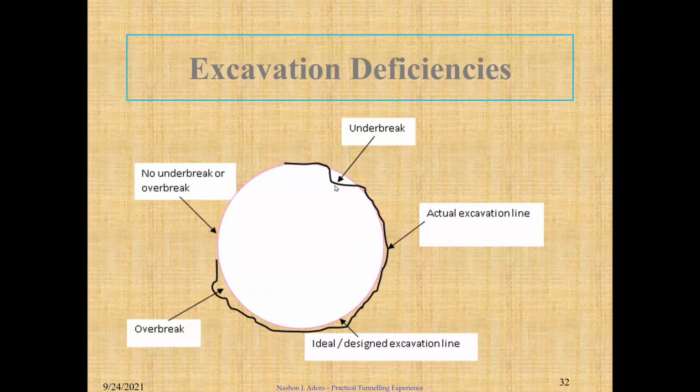So there's a way you have to measure those from the spring line as a surveyor, so that you give the workers how much underbreak this one is. Maybe if it is 3 centimeters, we write 3.3, so that additional blasting or excavation should be done here to get enough room. This is for excavation, not the final finishing, just excavation. And here, how much should be filled.